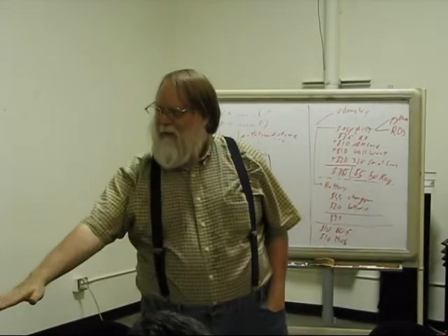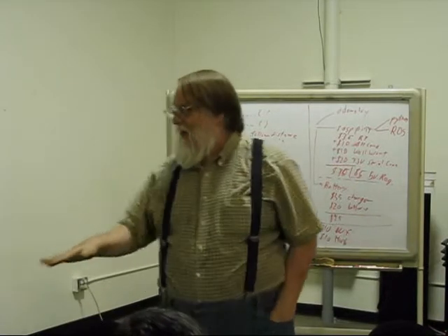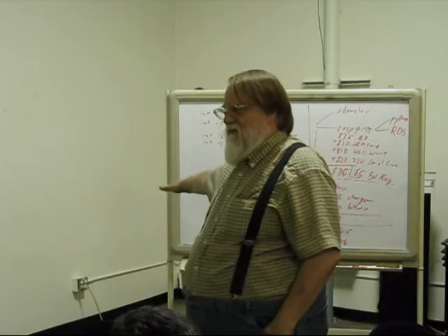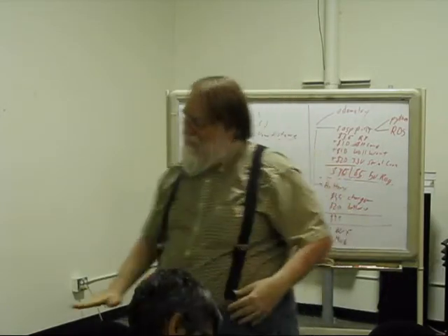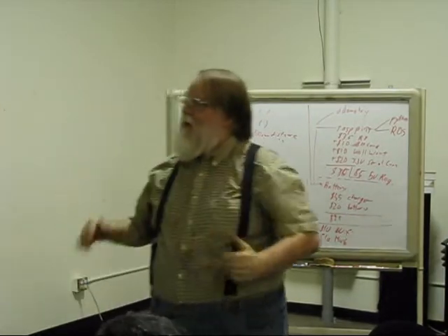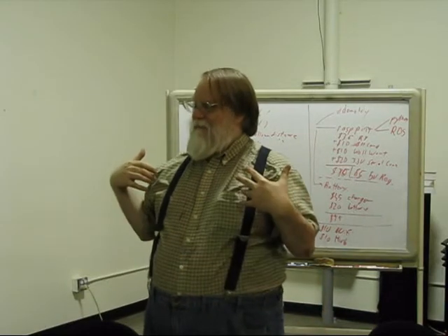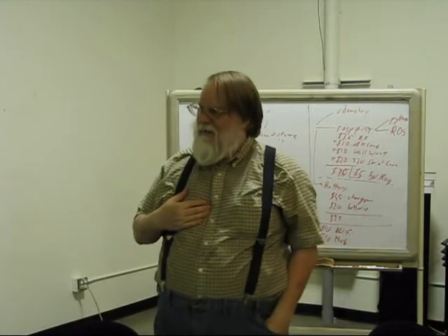The only difference between a tabletop robot that doesn't fall off the edge and one that doesn't hit the walls is that you have to convert the sense of the sensors, because when you go over the edge, the sensors go long. We want the exact opposite. When we get close to an object, we want to back up. So give it a try.